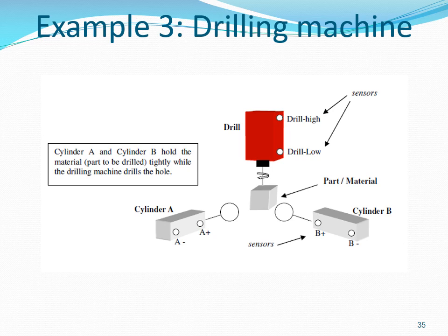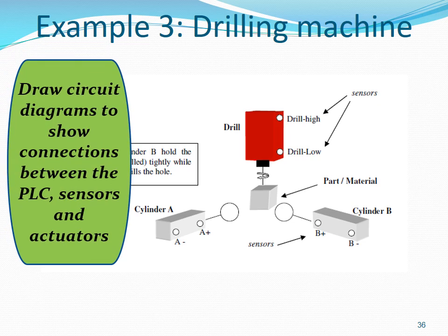And after finishing the drilling process, the drill has to be raised. There are respective sensors to detect the positions of the drill and the cylinders. Suggest suitable sensors and actuators and then draw circuit diagrams to show how these sensors and actuators can be connected to the PLC.